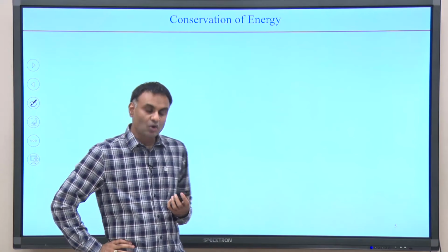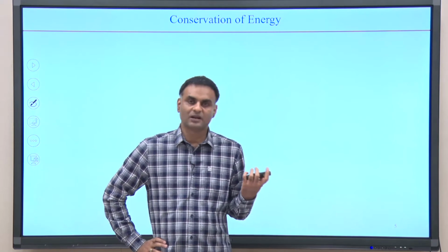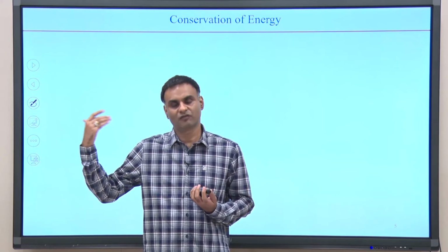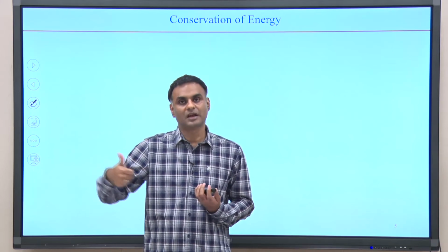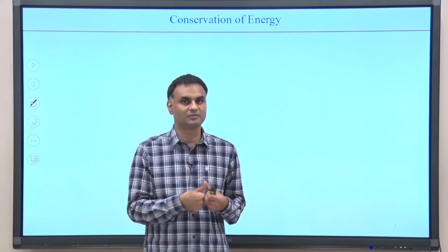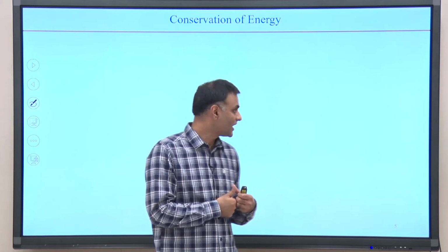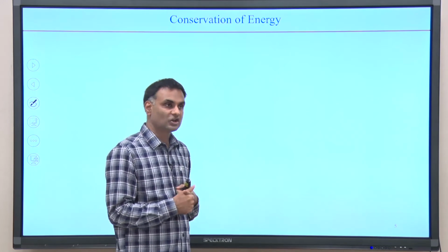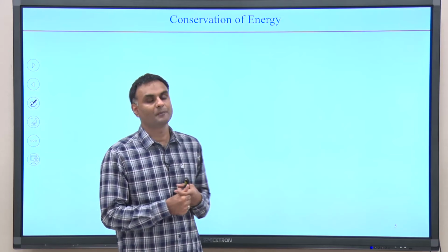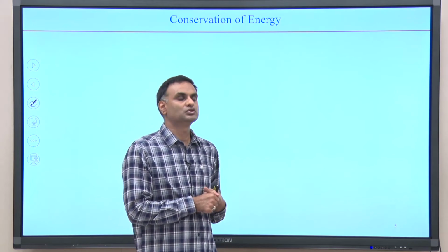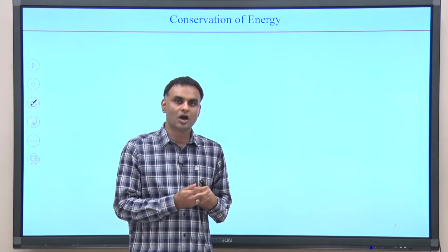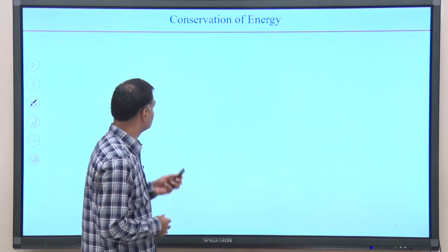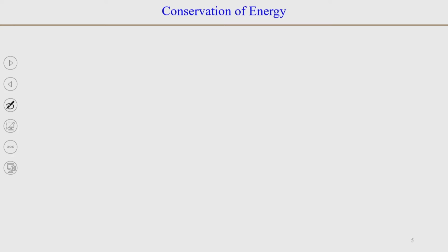So, if the flow is compressible, then we need to solve the energy equation, because we need temperature, and the temperature field may be changing because the velocities are high. So, we essentially need to always solve conservation of energy, but for incompressible flow we may need to solve it only when there is heat transfer involved, or the flow is not isothermal.